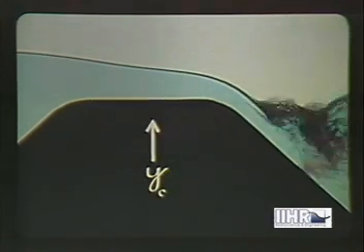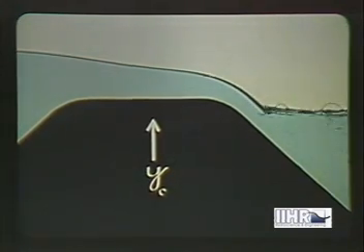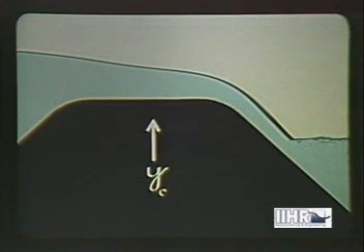Otherwise, the flow is closely analogous to that of water in the case of a local constriction. Under normal conditions, the flow at the constriction passes from the subcritical state to the critical at the crest as the tailwater is lowered. This corresponds to conditions of maximum discharge, which remains constant as the tailwater continues to fall.